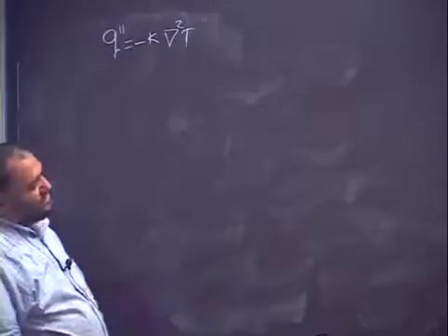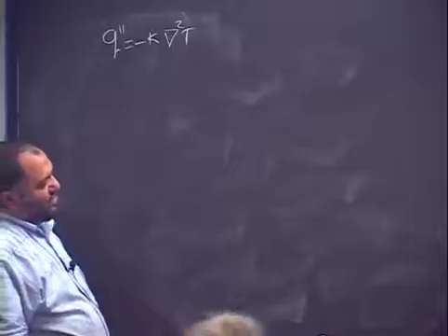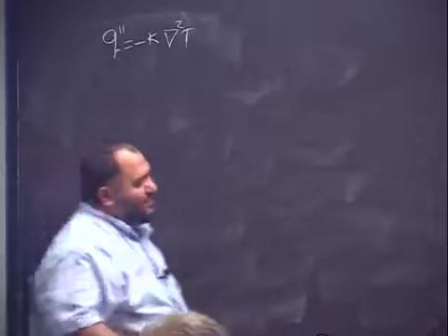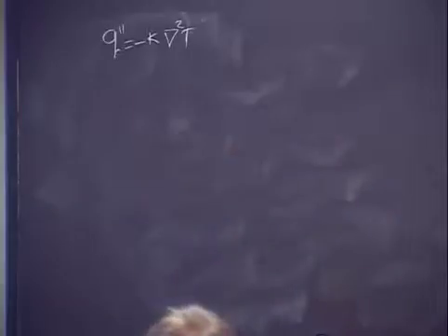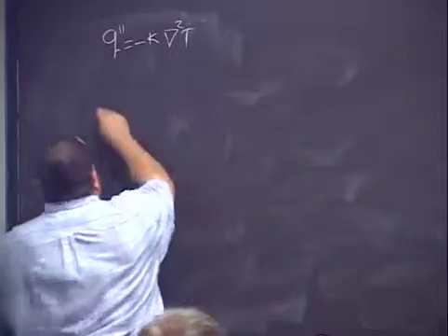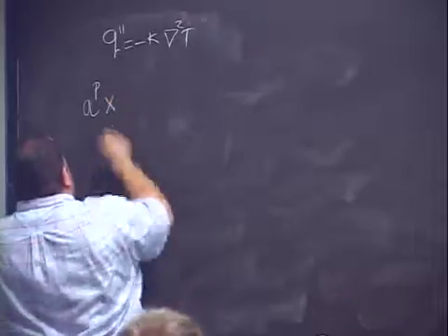So let's assume that we are solving the heat diffusion equation, and you want to integrate over the control volume centered around point P. In order to do this integration, usually you will have A P multiplied by the temperature.